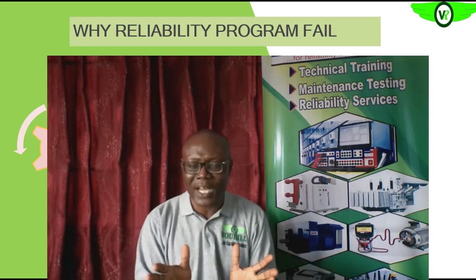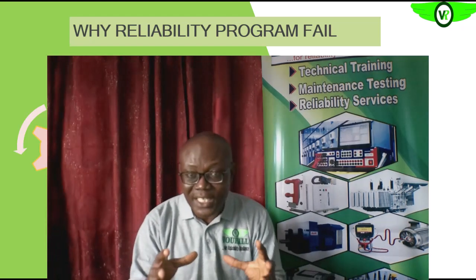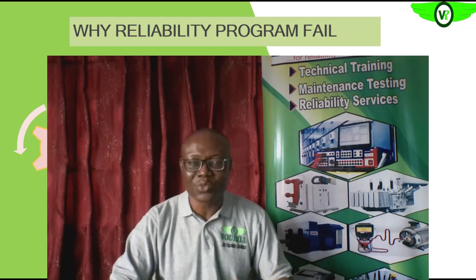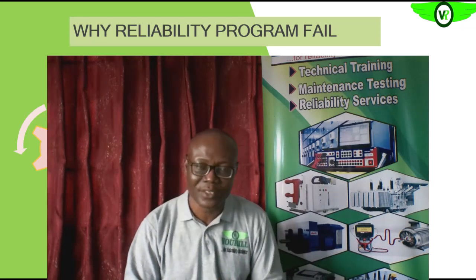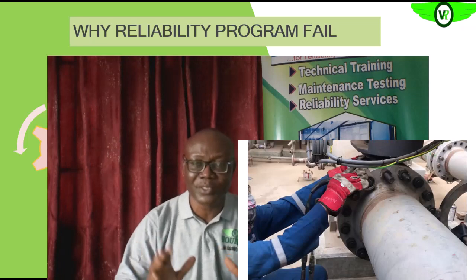What about if we have a standard process in place in making that joint? A standard material definition that tells us the actual gaskets to use, the size of bolts to use. Then we have the appropriate torque wrench, be it hydraulic or manual, whichever is appropriate for the making of that joint.